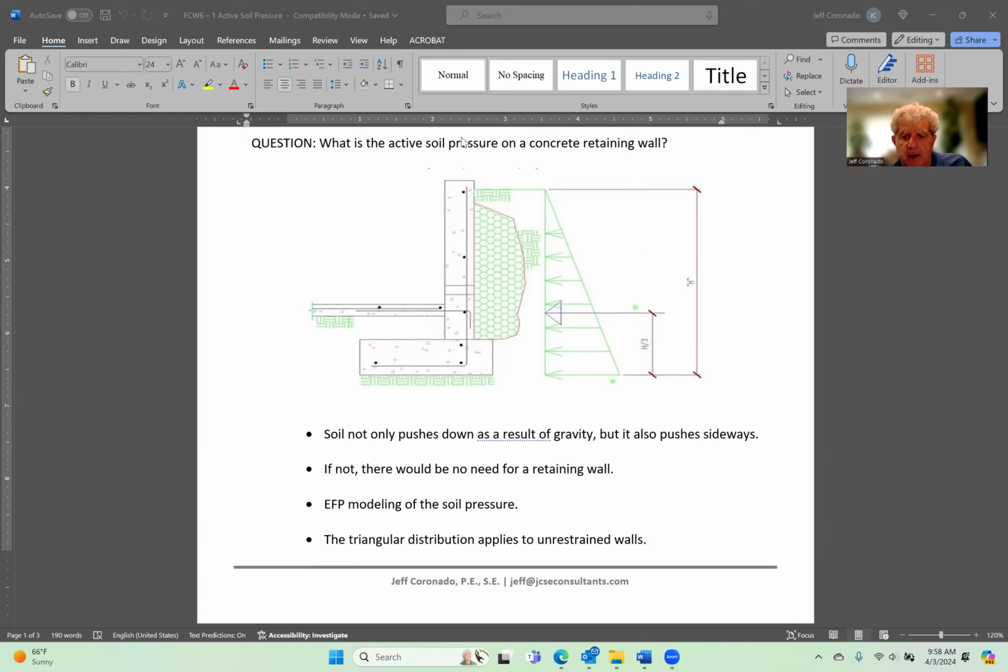So a pipe with holes, placed here at the base, on top of the footing. I might have drawn this a little too large. This might typically be a 4 inch or 6 inch pipe, and the perforations, the little holes in it, will be up here.